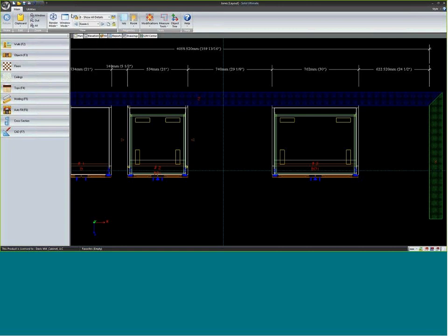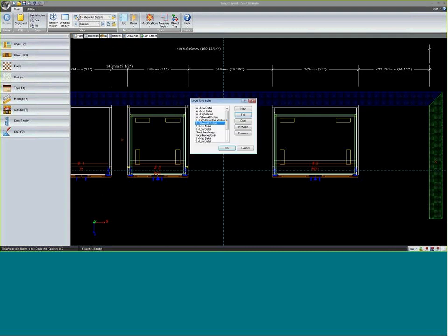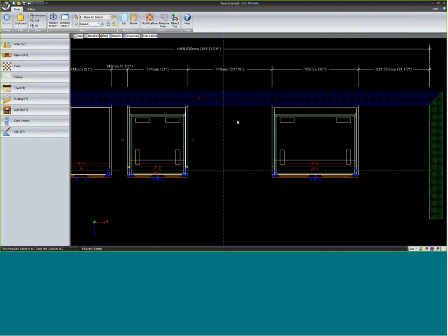So you would come, let's see, right, under this layers button, so layer schedules, and you could take one of these that you like and make a copy of it, and then rename your copy, whatever you'd like to call it, and customize that new copy. Now that new copy should stay. It should not be overridden by our catalog update. So you can customize that however you want. Otherwise, you can just use the layers that are already provided and tweak them as you need to.